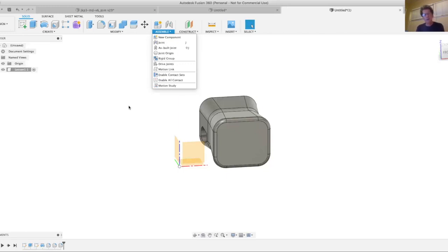When you import a complicated surface model into a CAD system, sometimes the import software doesn't do a perfect job. So you import that it's a mesh, and you have to make sure that it's closed in order to solidify it.